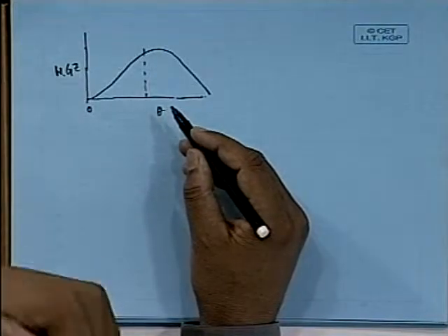I don't know how to put it this way, but without reason a ship cannot heel. Something would have applied some moment. So there is an external agency, somebody had to push it. If you are doing a model, you are pushing it by hand or whatever. So there is some work that has to be done. There is a force that has to be applied against a resistance. What is the resistance? As I push it, the ship is trying to actually come back to its original position. This is the resistive moment.